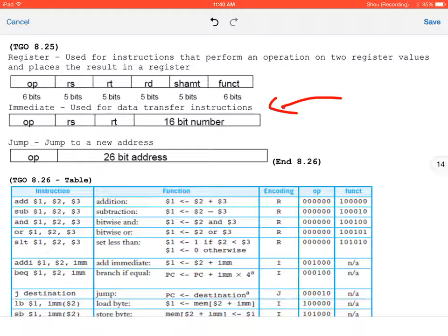If it's 32 bits, I have to shift left by 2 to multiply by 4. Let's say it was a 16-bit data path. I only have to shift left by 1, because I'm multiplying by 2, since I have 2 8-bit blocks. Right? So now let's go down to the 8-bit data path that you're using. How much do I have to multiply 8 by to get 8? So how much would I have to shift by? 0. Bingo. 0. So the data path is going to be a little different here.